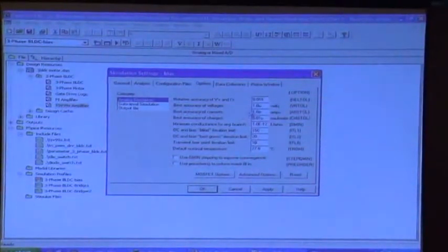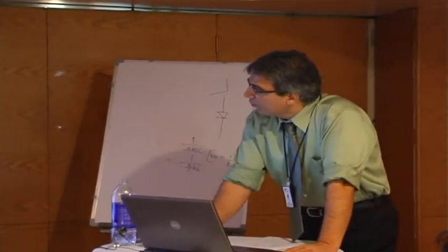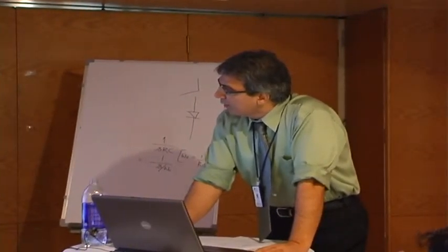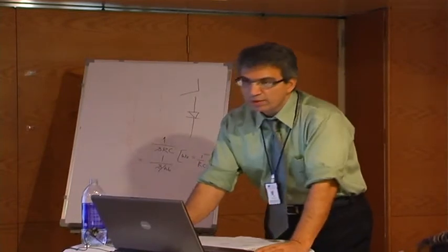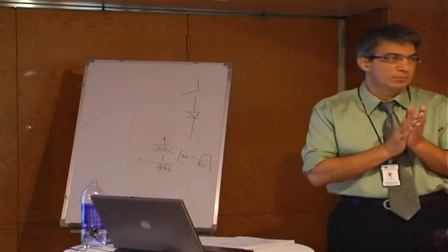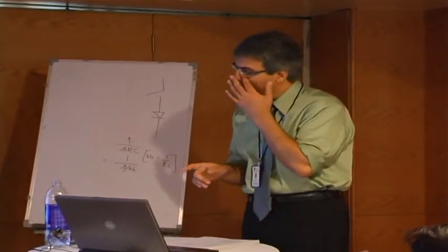So normally we play with the parameters up here, relative voltage 1, 2, 3, 4, 5. So we'll mess with these 5 parameters. ITL1 normally is changed to 400, and then ITL4 is normally changed to 200 when we run into convergence issues. Hopefully we will not run into any convergence issues during our demonstration.